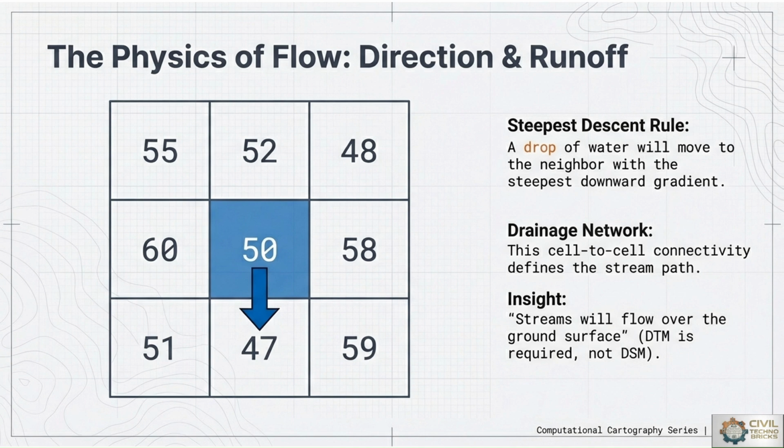By analyzing the elevation differences between adjacent cells, just like 55, 50, 58, the GIS software can determine the flow direction, that is, the path a drop of water would take to travel through the landscape. We use the D8 algorithm, which assumes water flows to the steepest of its 8 neighbors, just like shown for 50. The 8 neighbors of 50 are listed below. With reference to that, the D8 algorithm works the same way, and we can mark the path of water flow.